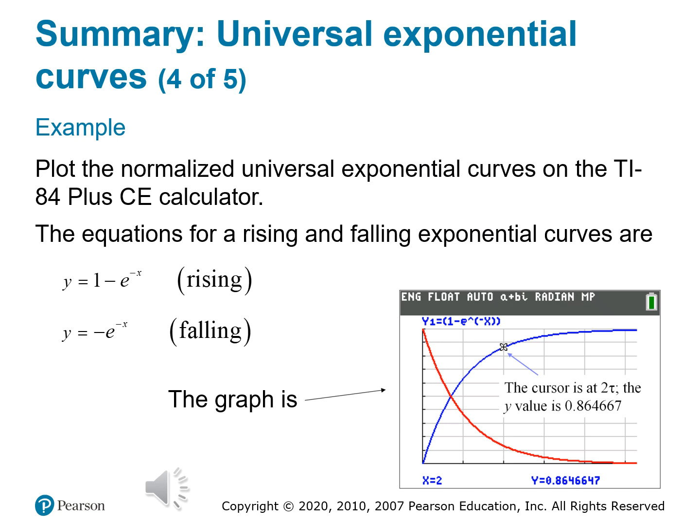Why is this useful? Because now you don't need to memorize a full exponential function or punch in long equations. Just remember that at 1 tau, one time constant, it rises to 63%. At 2 time constants, it's 86%. At 3 time constants, it's 95%. And when you get to 5 time constants, it's 99.99 something. We say it's effectively done. We say it's 100%, but it's very, very close. Close enough. And these numbers give you quick checkpoints for real-time design decisions.